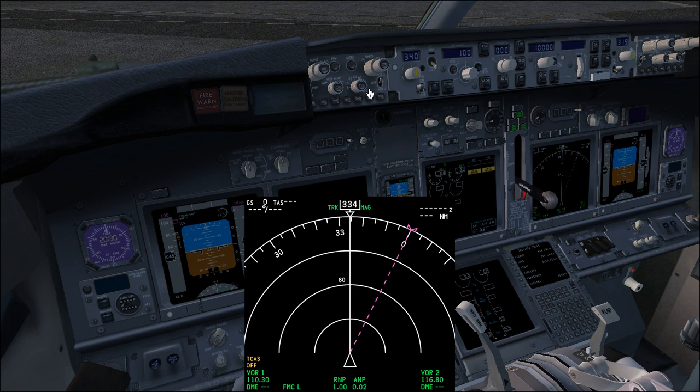The data shows constraints on the route. We will have some waypoints around the route. If we select those waypoints and the data button, the data button will show us the constraints on any waypoint you will pass, and also the estimated time of arrival for any waypoint on the route. The position switch, if you turn it on, shows the position of the 3 IRS and GPS receivers.